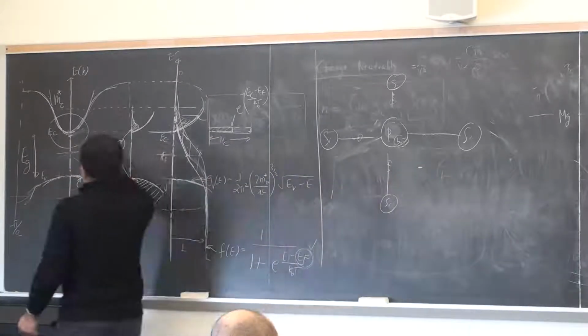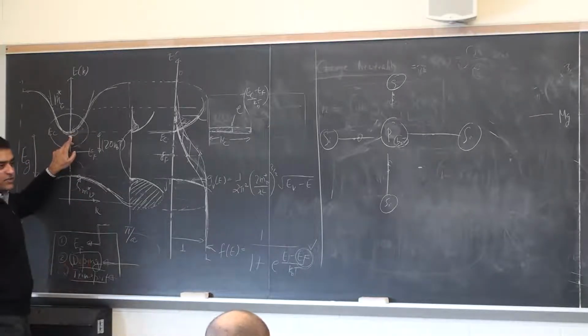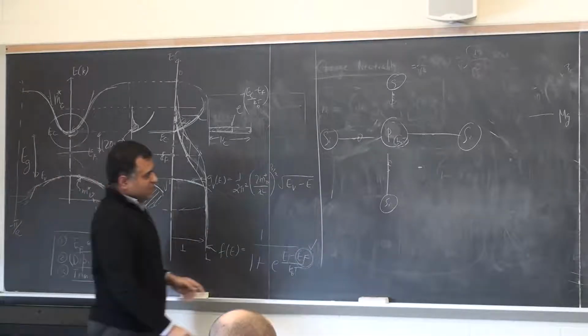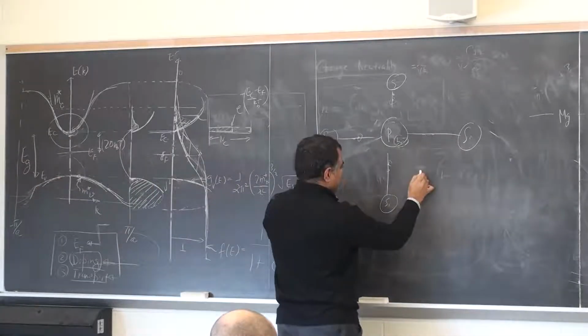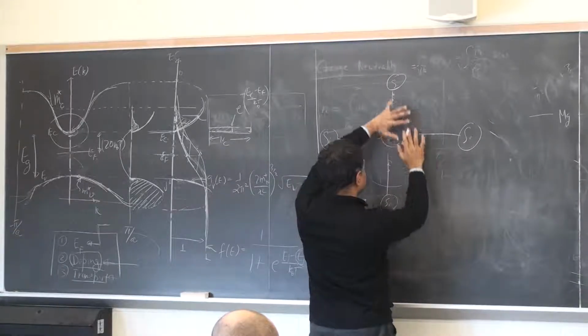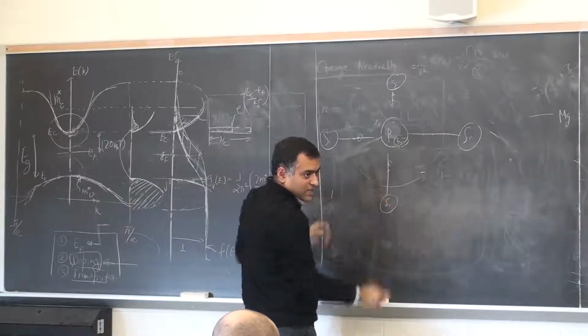That energy kT should be able to kick it out and put it in the conduction band, and that electron is not bound to phosphorus anymore. It's free to move in the crystal now. So that's the meaning of doping. Ordinarily, if the phosphorus atom was able to bind it, it will hover around here and it will not respond to electric fields. It will get stuck. That's a localized electron.